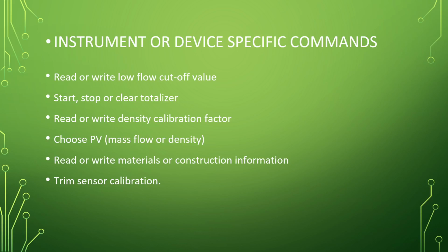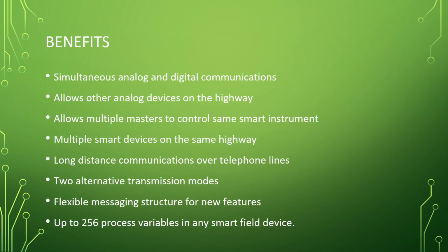So the HART protocol. A lot of benefits here. We have both analog and digital over the same wire. That is assuming one device. So that is something important to keep in the back of your mind. I guess you could technically, and I'd be really intrigued how to do this, but you could probably hack it and put a HART device that is set up for digital only and an analog device, analog only, and still have both of that information coming at the same time.